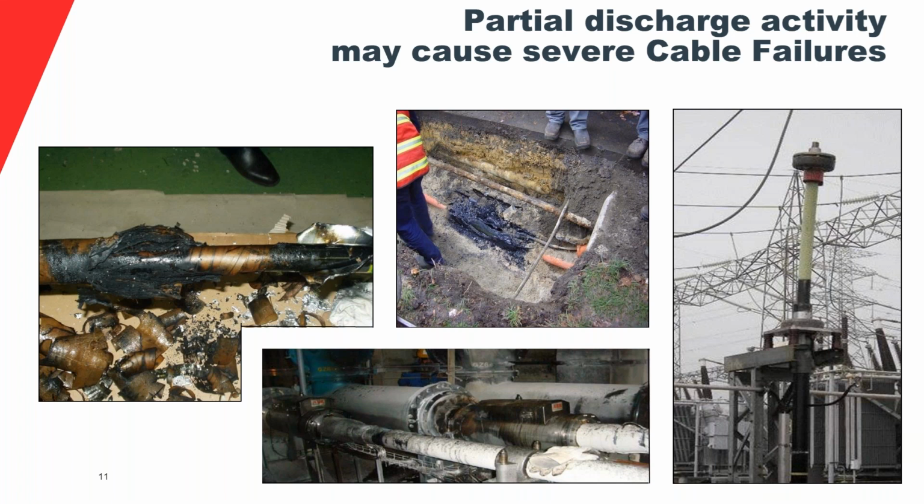Then on the bottom, you see a gas insulated installation that exploded. And this is one failure, and it took them months to clean up that failure in the first place before they could do a fairly straightforward joint repair or splice repair and put that transmission cable back into service. But you see all this white byproduct, and this took forever to clean up.